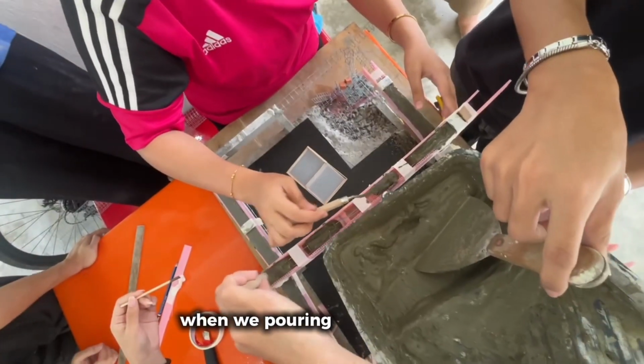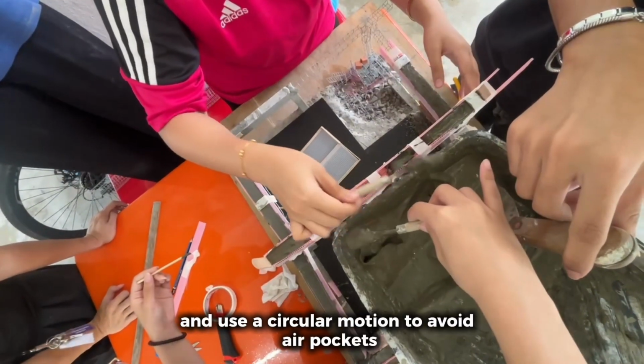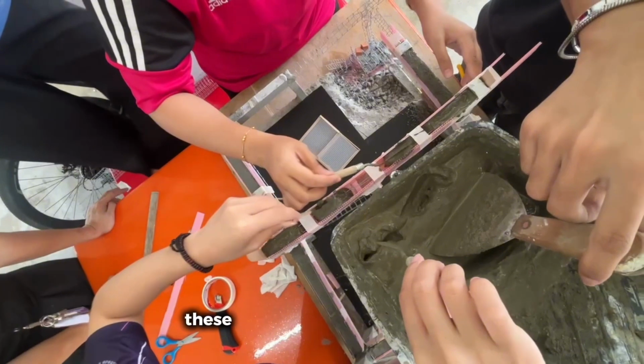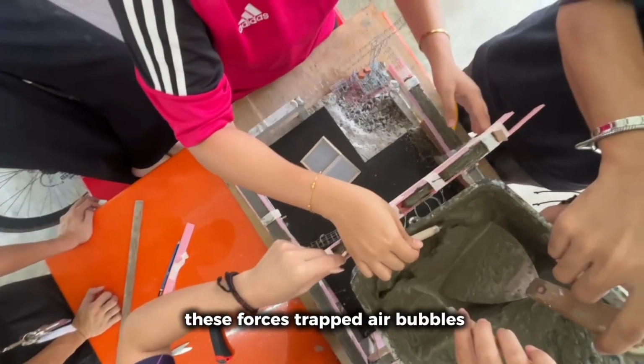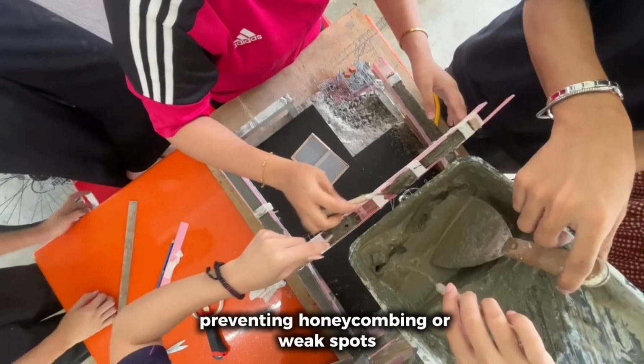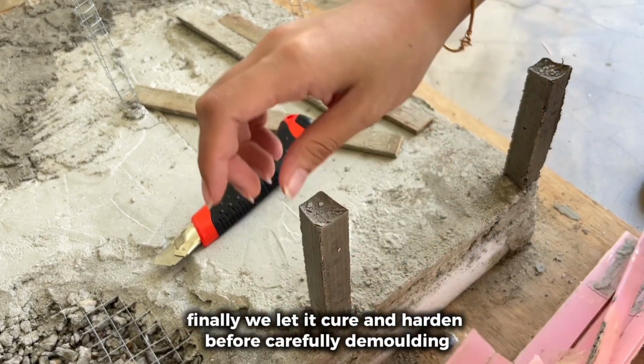When we are pouring, we start from a low point and use a circular motion to avoid air pockets. Crucially, we must vibrate or tap the mold. This forces trapped air bubbles to the surface, preventing honeycombing or weak spots. Finally, we let it cure and harden before carefully demolding.